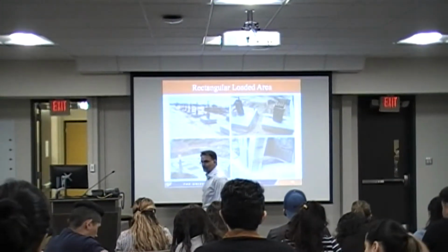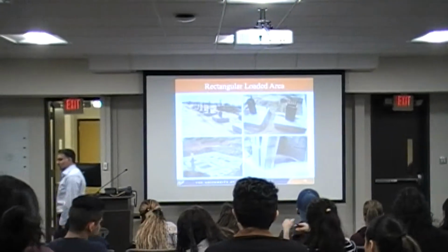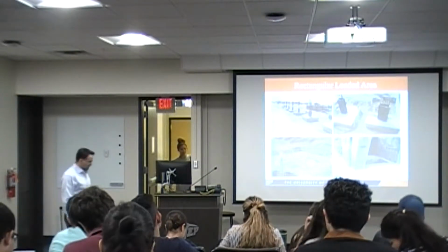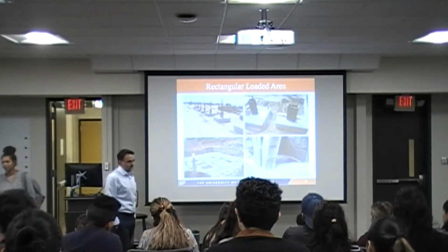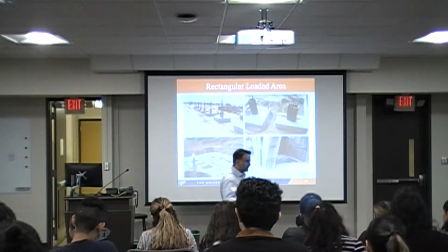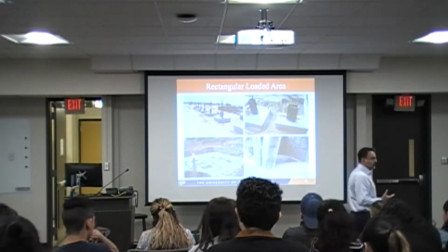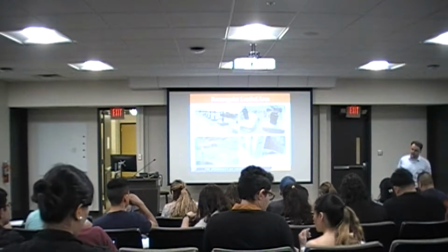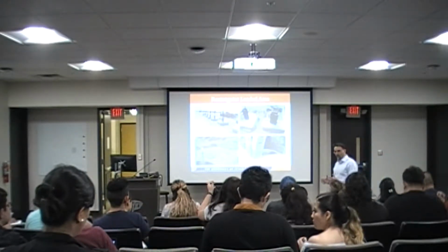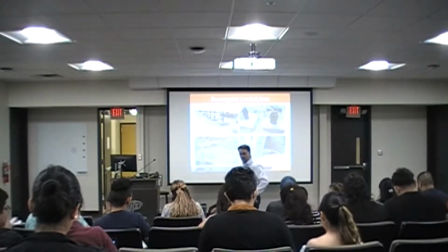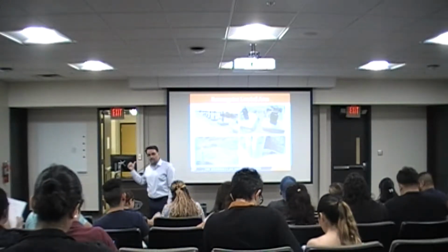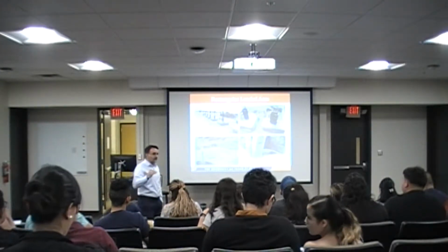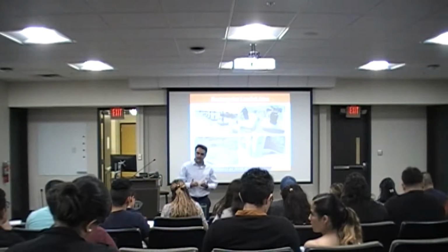Alright, so quickly let's talk about a quick review of what we talked about in terms of the external loads. Remember the type of loading that we have, the major type of loading that we concentrate on are geostatic stresses, the stresses associated with the weight of the material, and also we look at external stresses, or stresses associated with loading conditions that we have. For instance, if you have a structure placed at the top of the soil, that could be a bridge, that could be a fountain, that could be a building, it could be an earth dam, or the embankment that we saw in previous lectures, that induces some stresses at the top of the soil. Right? And those stresses can essentially cause failure of the soil.